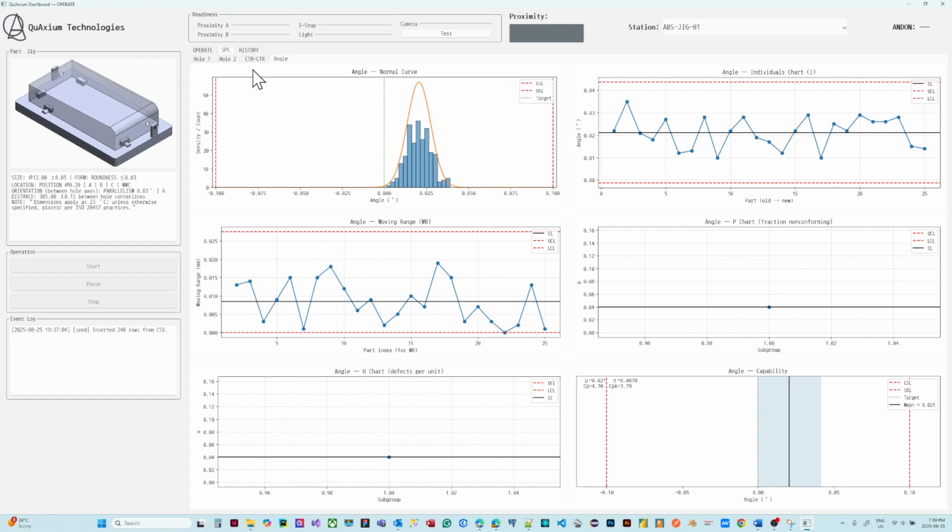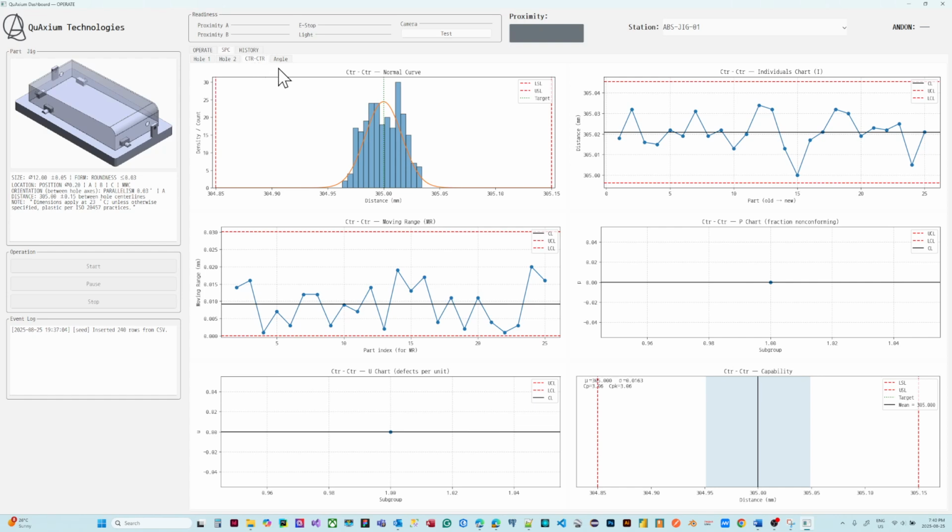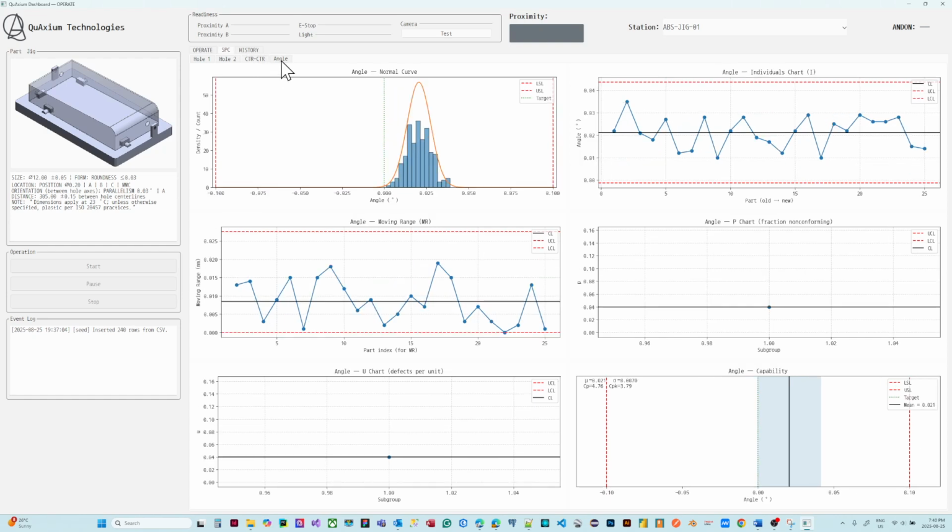Okay, before I move on, I would like to first tell you what those holes are. We are measuring these holes, hole 1 and then hole 2, and this is your sensor mount. Okay, so we check the diameter of the holes. We have here the specification, which is 12 millimeters plus or minus 0.05, the center to center, and then the angle.